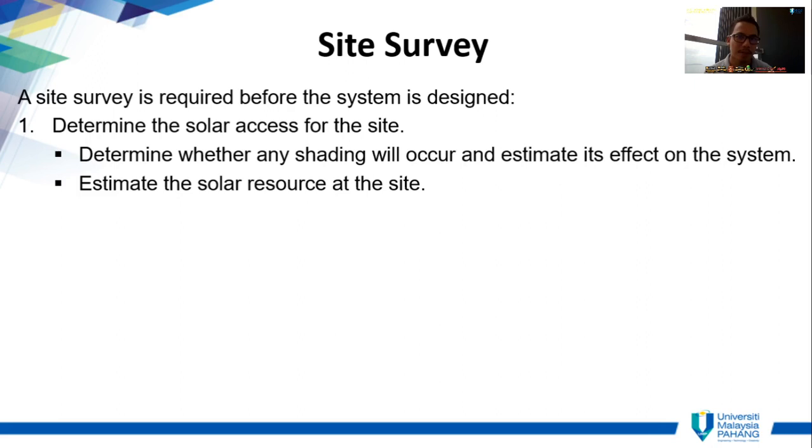When your PV system is blocked by obstacles like trees or nearby buildings, it will create a shadow on the surface of your PV modules. When a shadow exists on the surface of your PV module, it will totally degrade the output of your PV module. So the generated current will significantly reduce due to the existence of the shadows.